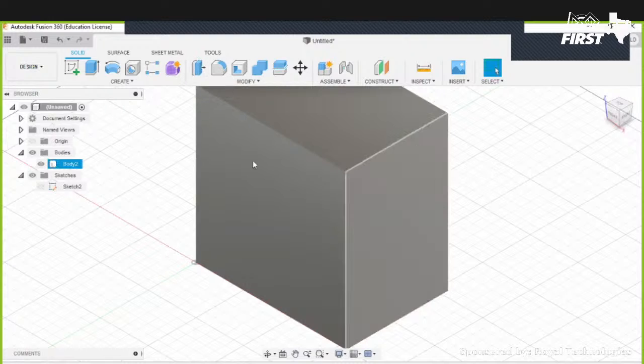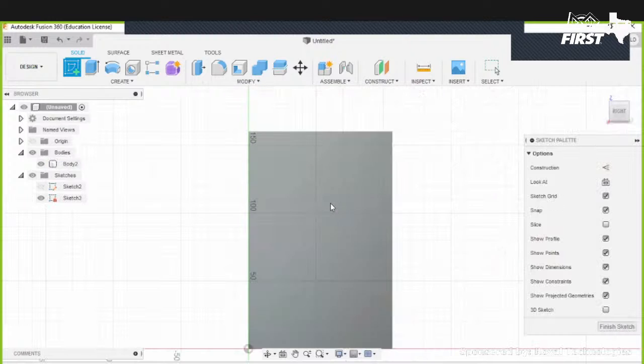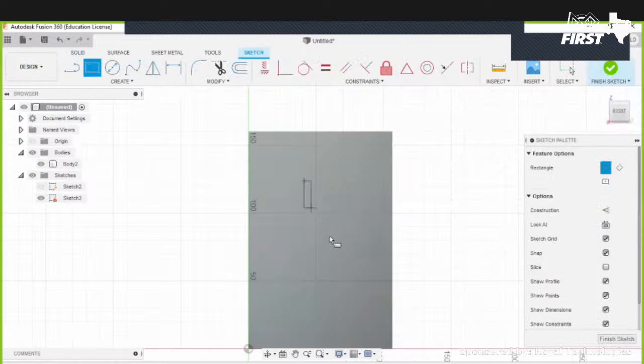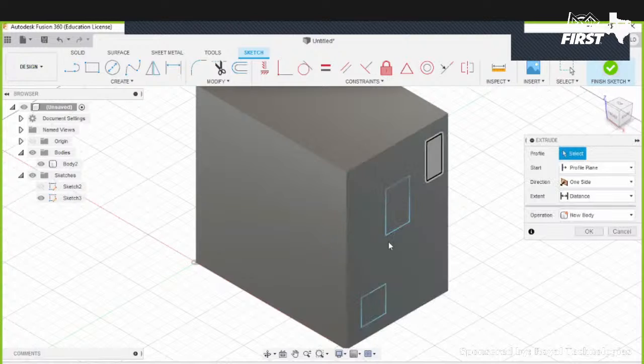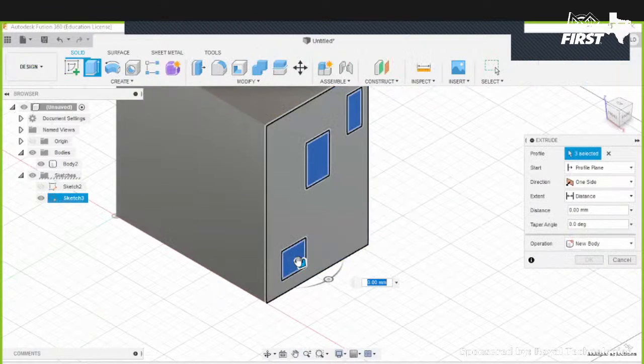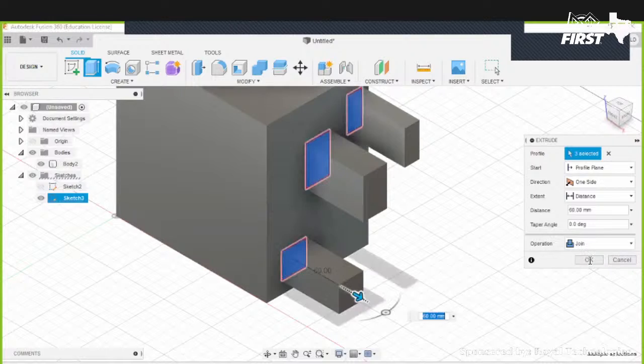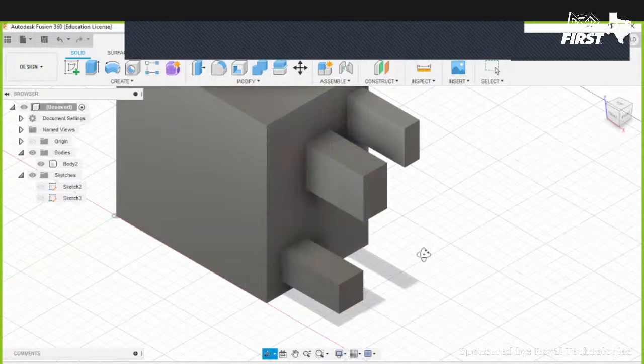So let's go ahead and try something a little bit interesting. Let's create some more complex shapes. Let's try making a sketch on this plane here, and I'm going to make a few shapes. This is entirely for experimentation. I'll pull out each of these. Notice there are different extrusions, and I'm joining. I'm not creating a body or component, I'm joining. When I join, it makes these three newly made cubes equal with this other original cube. I'll click OK. And so there we go.